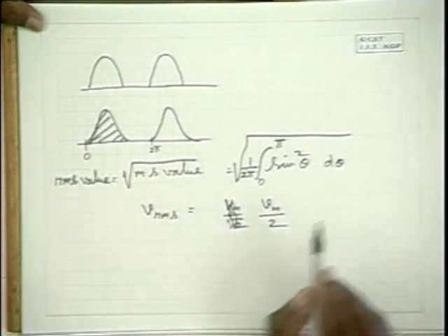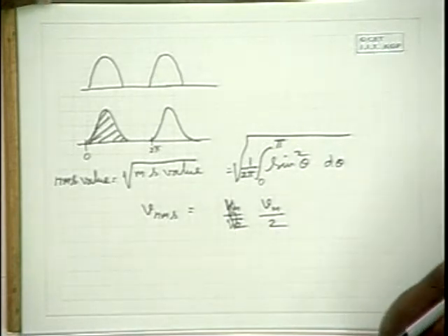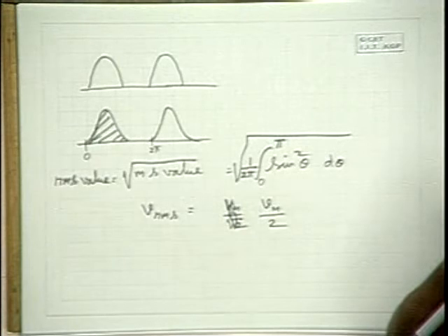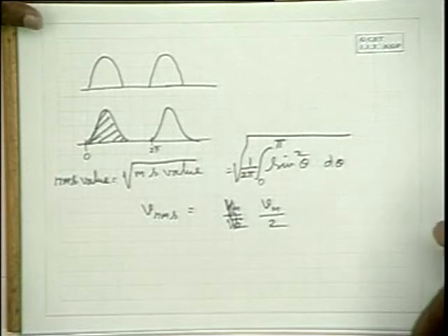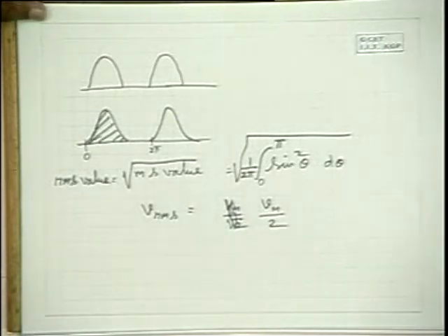So this is the RMS value. The mean square value is doubled in this case because the area of the square waveform when integrated is getting doubled. RMS value is under square root. Therefore, whatever is the RMS value you have previously, this will be 1 by square root of 2 times of that. Therefore, Vm by 2 is the RMS value here for full wave rectified waveform.